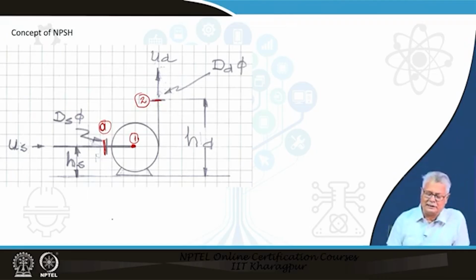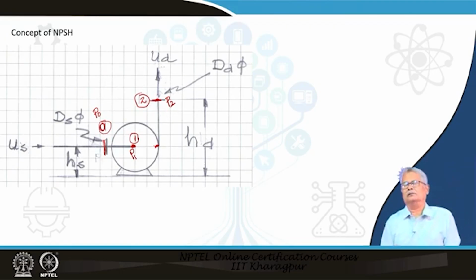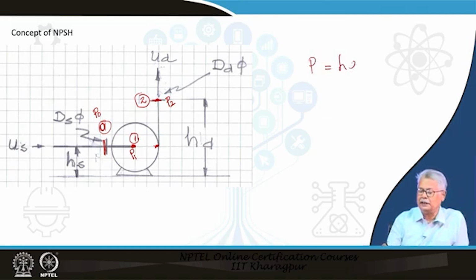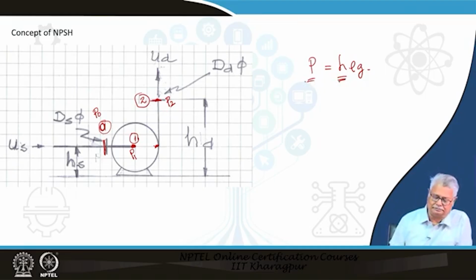Now, you know very well that in a centrifugal pump you have a pressure here which is P0, this pressure will be P1 and the pressure here will be P2. The difference between the pressure at this point and this point is practically a very short length. So, I will say that the P2 pressure is here or here. At the tip of the periphery, the pressure is P2, the total head is P2 and it is same. I could also relate, instead of P, I could also talk in terms of H, that is P over rho G, and this is the head. So, I am going to use either H or P.